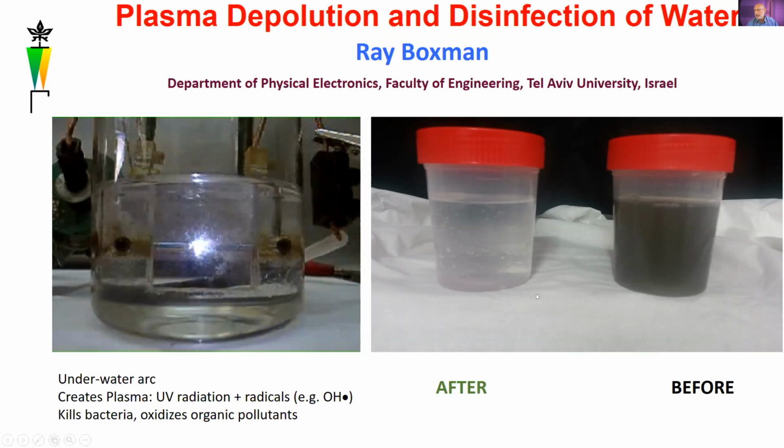And here's the thing. If you have a very, very polluted process water, for example, from a chemical plant, we can use this process to get this result. Basically, you can reduce the total carbon concentration within the water from very, very high values to values which are more readily disposable by, let's say, more conventional technologies such as bioreactors.